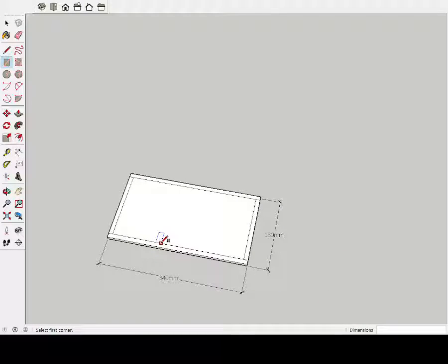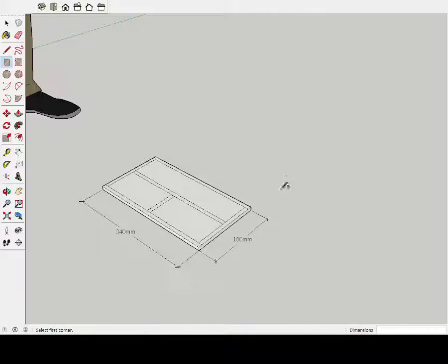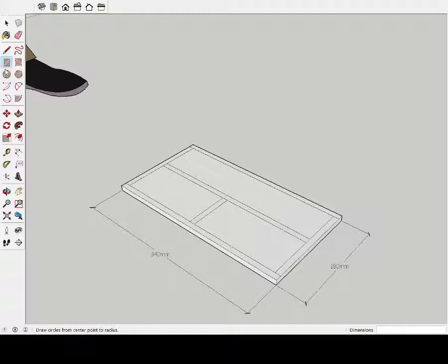As well as that, on this particular one, there is a box which goes along by 80. So I'm going to do 160, comma 80. And then I'm going to draw another wall on the outside of this, which is now going to be 80, comma 10, and so on. What I'm doing is building up the walls on the inside as well. Okay, so this is going to be 320, 10, because all the walls are 10, and that's sort of my floor plan, if you like, for the